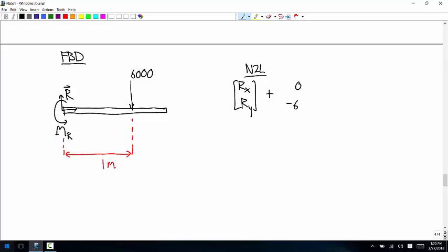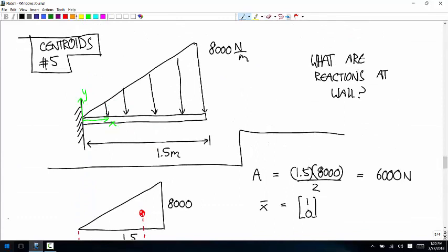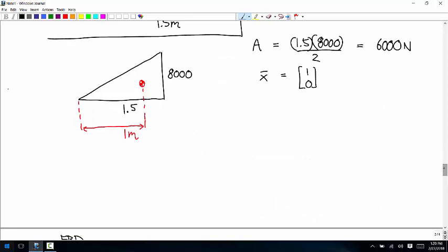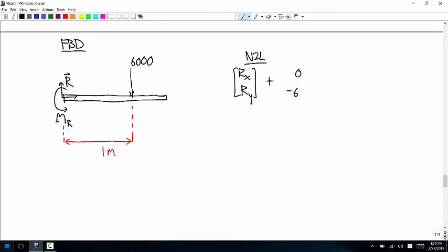You know what? I forgot something in this one. It also includes a weight. Okay, so the mass is 75 kilograms. So we calculated the stuff we need for this distributed load. We also, in our free body diagram, have to include the weight force. So that acts right at the center. And it has a magnitude of 75 times 9.81, which is 735.75.